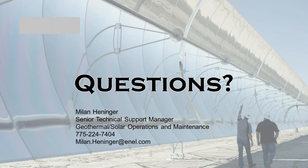Great, great. Yeah, we've had a few come in, so we'll toss these to you now. Someone was asking, with the UltraProbe 10,000, what setting you had it at when you were listening to your VFDs? Yeah, so in that situation, we were using your standard electrical inspection technique. So it was set at 40 kilohertz and maximum sensitivity.